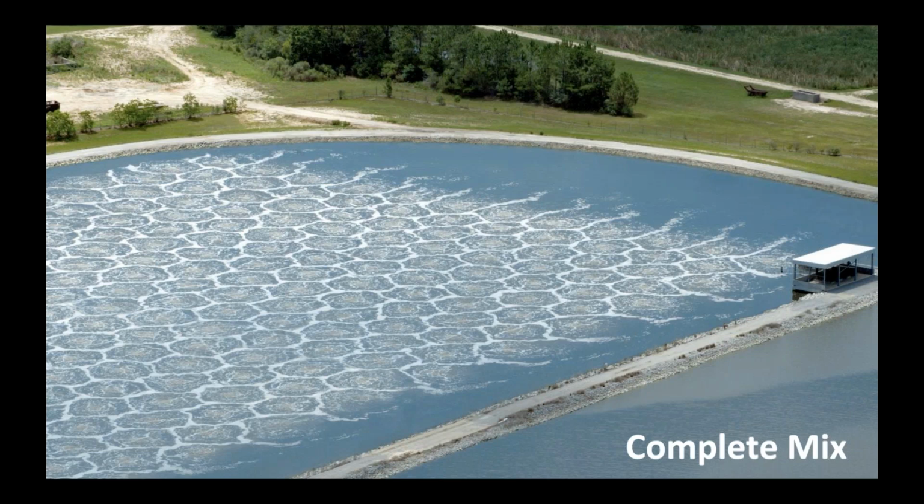The downside of complete mix is you do need a lot of air. It takes a lot of air to do this. It takes a lot of aerators to get complete mix. And so unless you have a specific footprint requirement or a need, you're probably better off not having complete mix, to be honest with you.